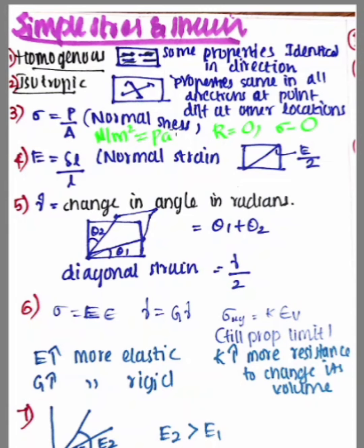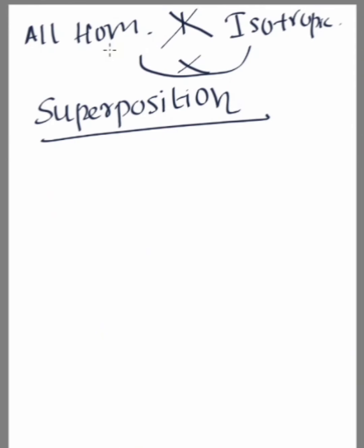Okay, that is regarding the stress portion. You should study what superposition is, the limitations of superposition, the validity of superposition, why it is not valid, and in which structures it is not valid. This is a very important topic you should remember for all kinds of examinations. At least you should know the limitations of superposition. The load will be within the proportionality limit only, so Hooke's law is valid till the proportionality limit only. The second limitation is that the deformations are very small. Talking about validity, it is not valid for T beams and non-circular members subjected to torsion. You should remember these two points.